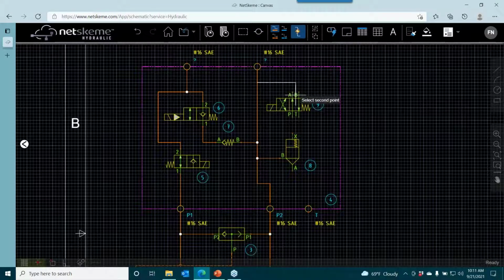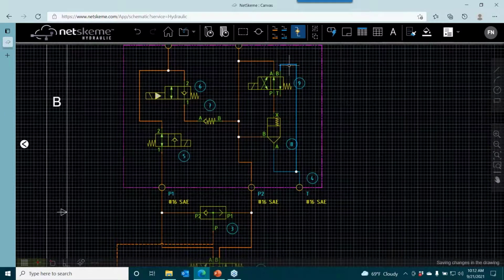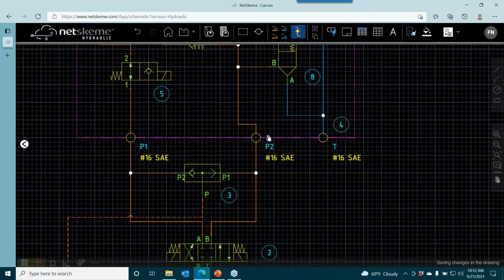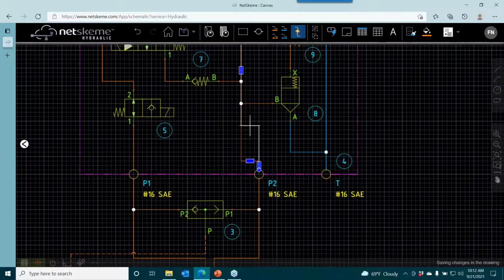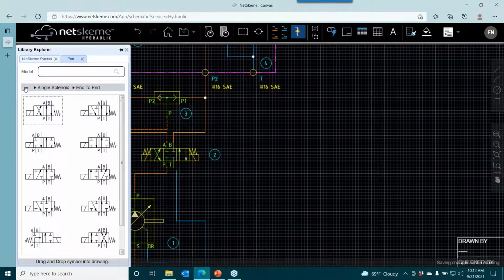And I'm going to make our connections. And I'm going to move our tank port here. Looks like we have a connection line problem there. That is something coming up in the next release. Our connection lines should be adjusting a little better. So some of these unnecessary bends should be leaving, and some of the more special cases will route a little better. Looks like I did not click right here. So now let's connect right here to our reservoir.